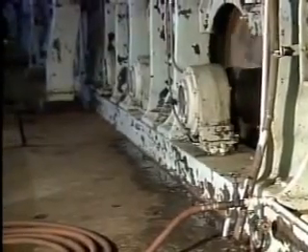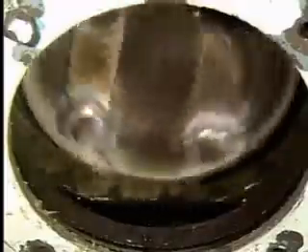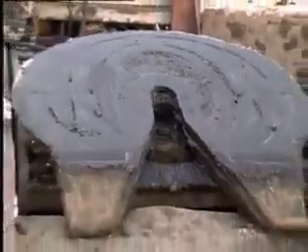Oil is also important as both a coolant and as a lubricant in bearings. These bearings support large, heavy rollers. The friction produced by the heavy load can build up a lot of heat in the bearings, but the lubricating oil flowing through helps keep them cool. Oil's ability to flow freely can make it unsuitable as a lubricant in some situations. In situations where a lubricant must stay put, a different type of lubricant, such as grease, is needed.